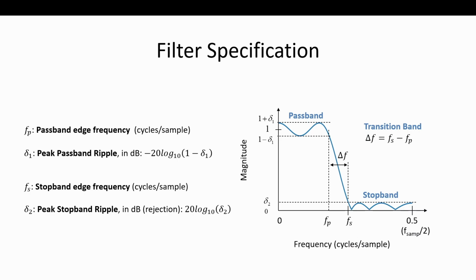And that would be an FIR filter where all the coefficients are 1. You're just accumulating all of them over a certain time span, and that's your memory. You're taking the current sample and all the past samples for a certain amount of time and averaging them. Accumulating is just like averaging. You just didn't divide by the number of samples, and that's the pure average, right?